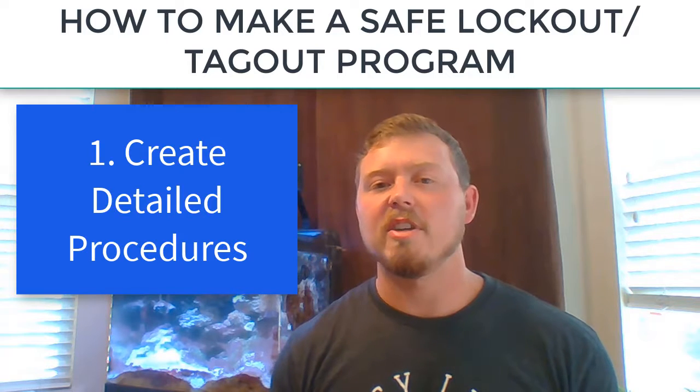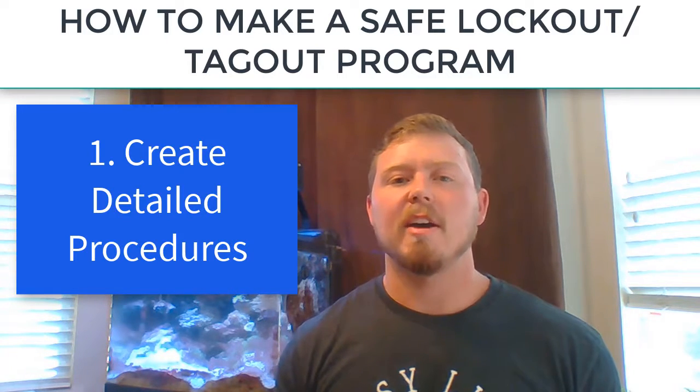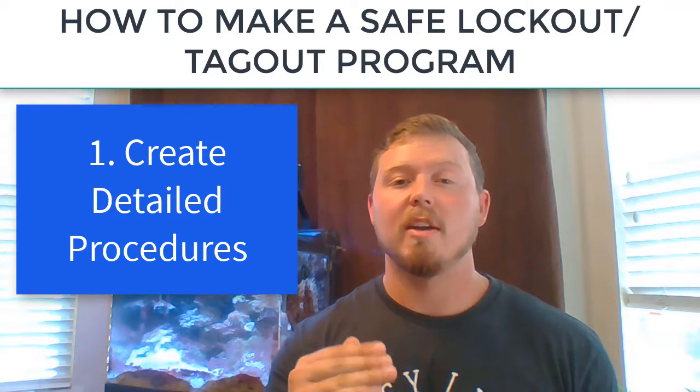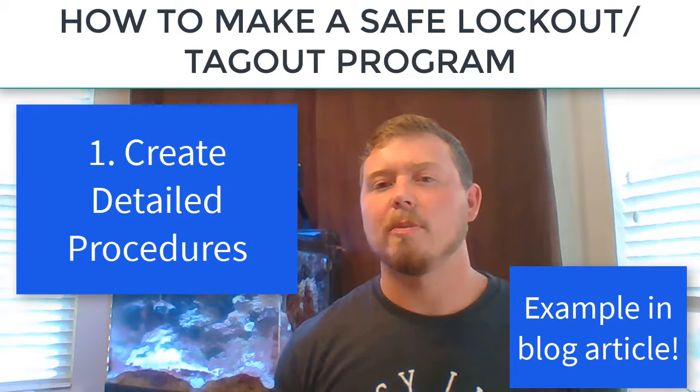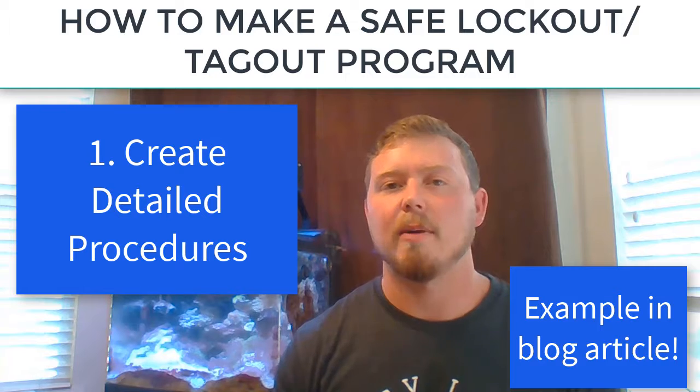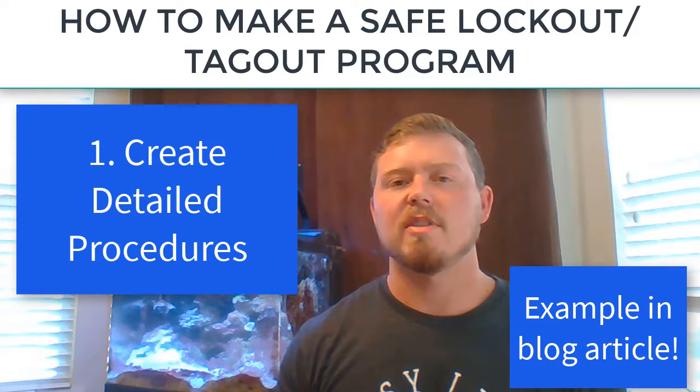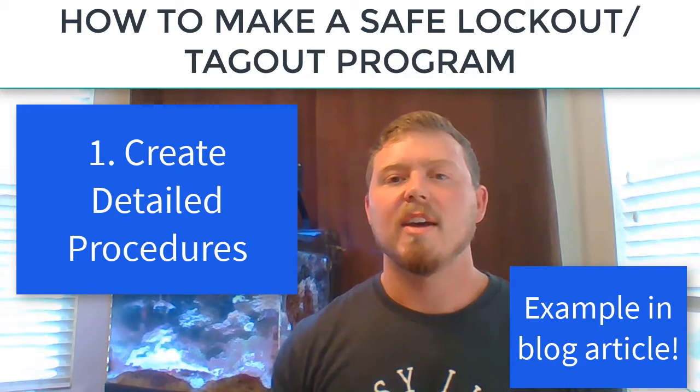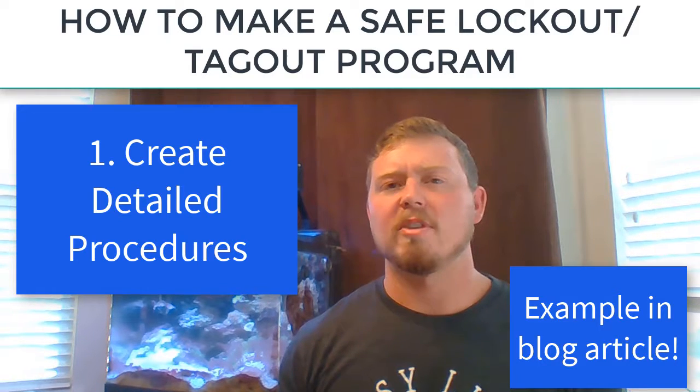Determine the correct procedure for shutting the machine down and starting it back up, and put the procedure into a list format. Once again, I recommend including pictures of each step as well as the energy source such as electricity or pressurized air. Also address secondary energy sources such as heat, fumes, or tension, and hazards that may need to be moved or tied down.